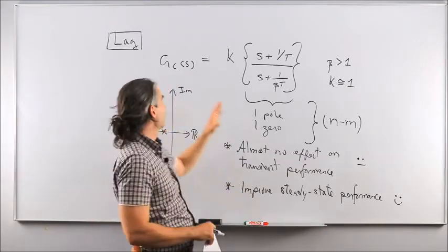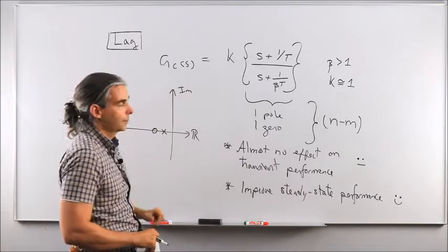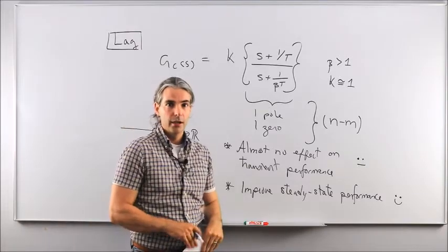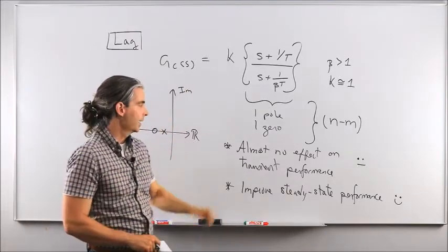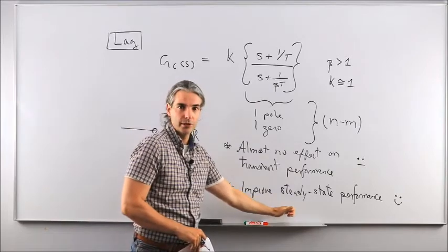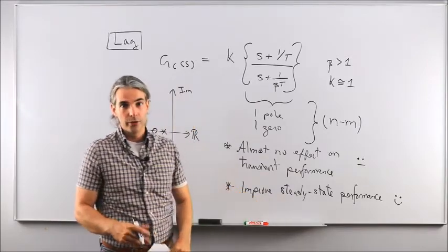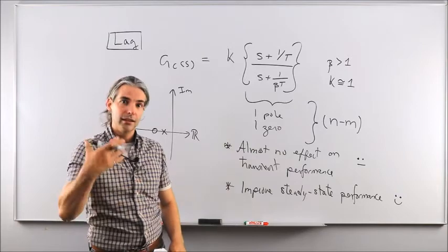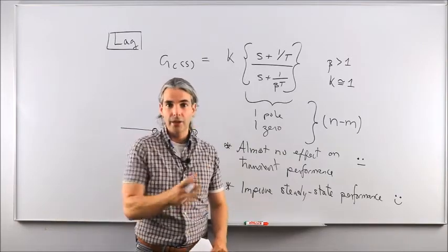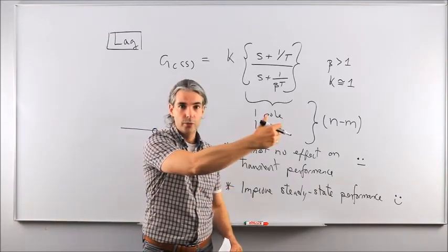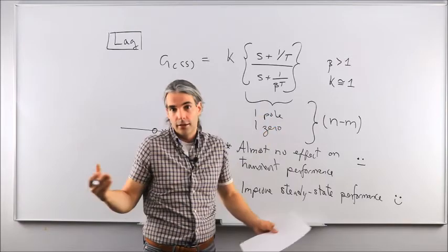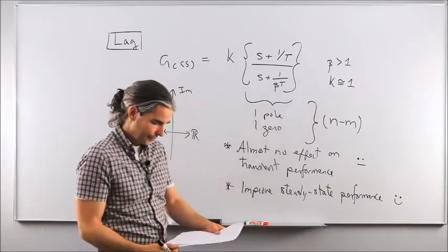You're going to pick either a lead or a lag compensator respectively. Lead to improve the transient and lag to improve the steady state performance. If you need to improve both, well, feel free to cascade a lead with the lag compensators back to back in the open loop direct path. But that will work fantastically, okay?